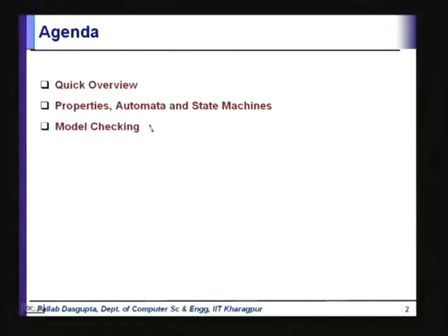Okay. So, model checking is not just something about verification of circuits, it is a generic methodology where you have some specification and some implementation, and you are trying to figure out whether the implementation is a model of the specification. It is not equivalence checking, because for the same specification there can be many valid implementations. Those implementations may not be equivalent in the logical sense.